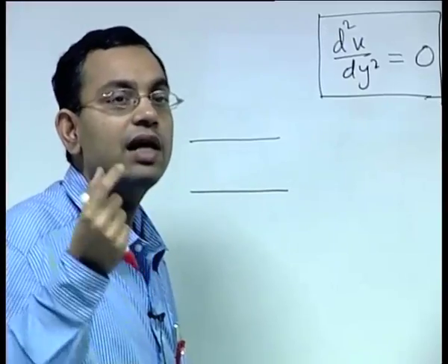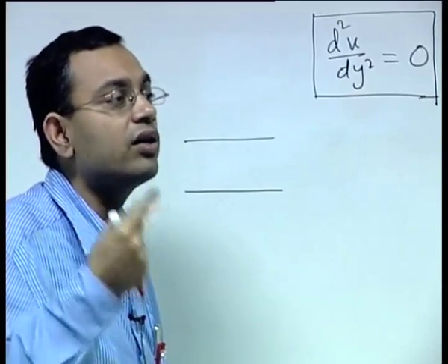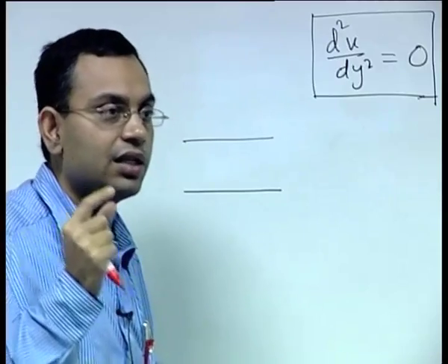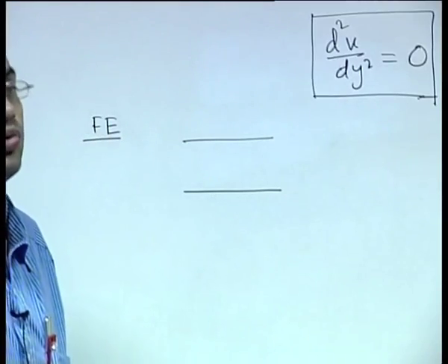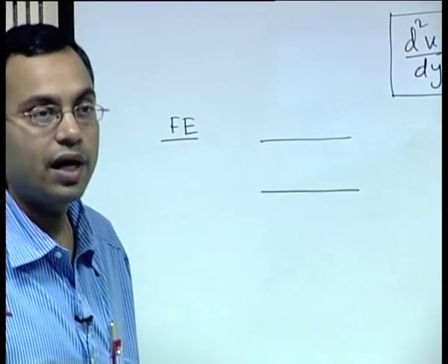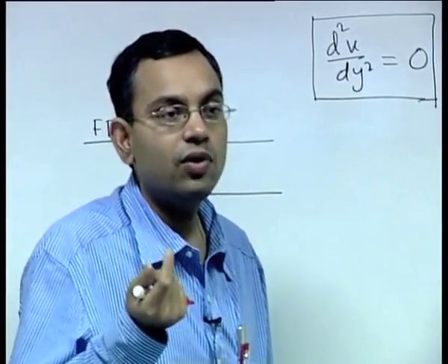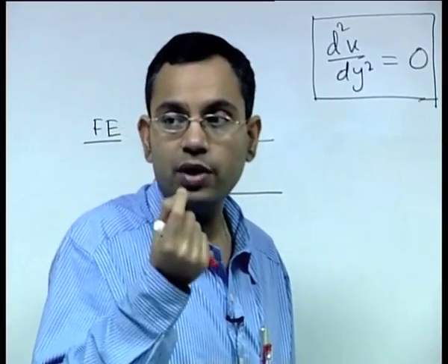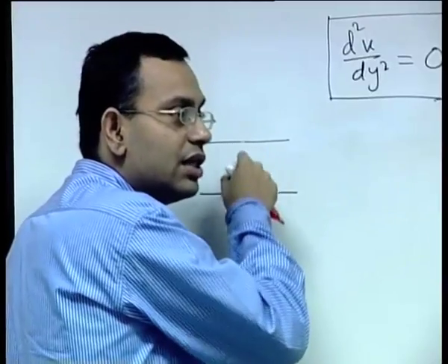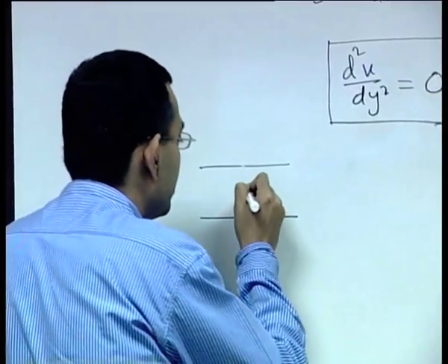What happens if one element has 3 nodes? Then you could have taken just one element, but then you would require a higher order interpolation function, a higher order shape function. But if you want to use a linear interpolation function, then your unknowns per element will be 2. So, you will have a 2 noded element, then at least 2 such elements will be required. So, the minimum number of elements required will depend on the order of the polynomial that you are using for interpolating the function. If you use a higher order polynomial, then you can use a single element, but maybe with some interior node points within the element to accommodate the higher order interpolation function. But here we will use linear elements.